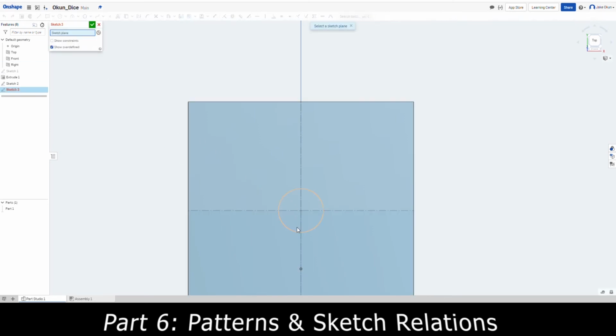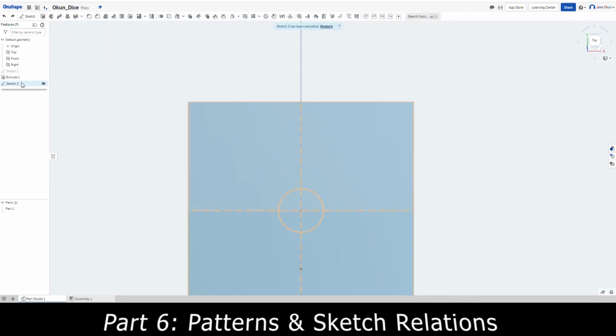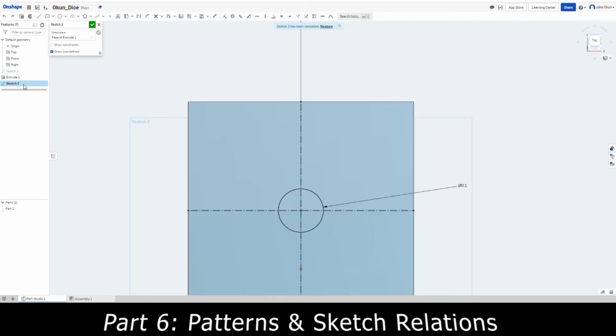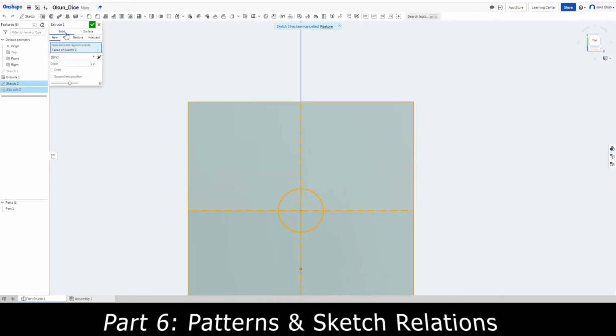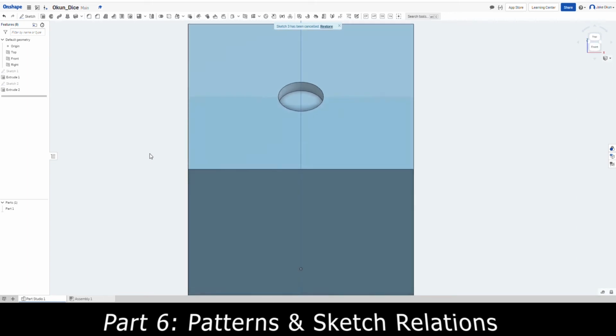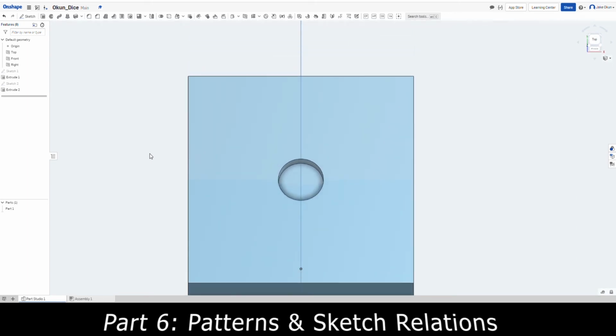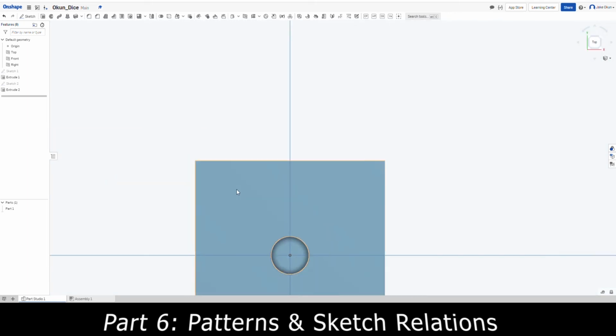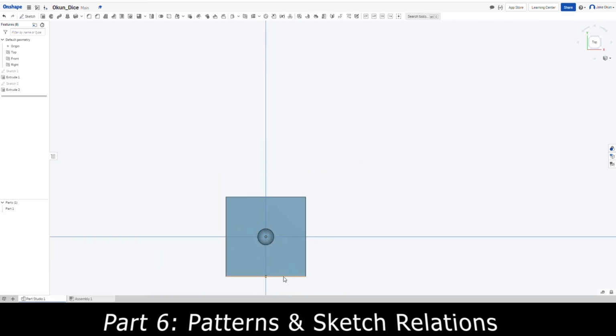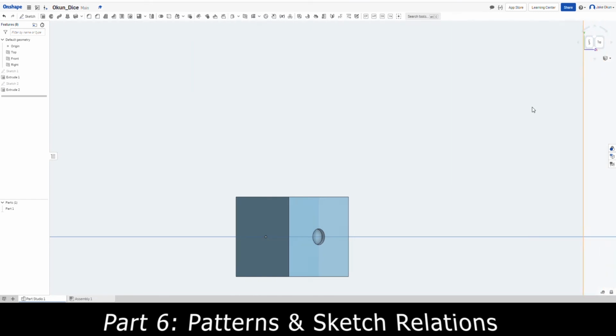And then I'm going to press Sketch and then select where we were before. So I'll select our sketch, double click, and then we'll go back and we'll redo it. Remember, we want remove this time. Then we'll stick our 0.025 inches. Perfect. Now let's see if that looks good. And that looks good. It's starting to look like a dice now. Perfect. So now we're going to move on to the other side. To do this, I'm going to just use my arrow keys and then move on.